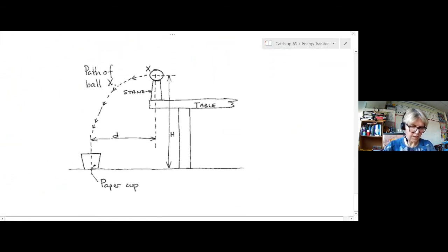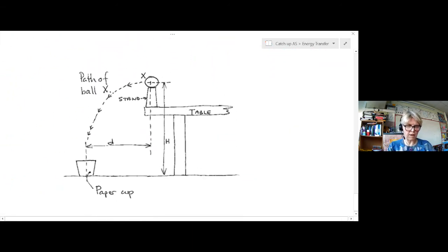I'll try and pull it up. Now we've got the bottom half. What we've got is a horizontal velocity going this direction, and we've established that that is square root 2g brackets L minus L cos theta. Remember, the only two measurements that you were given are the angle and the length. Now, what we need to also measure is the height. So that is our third measurement.